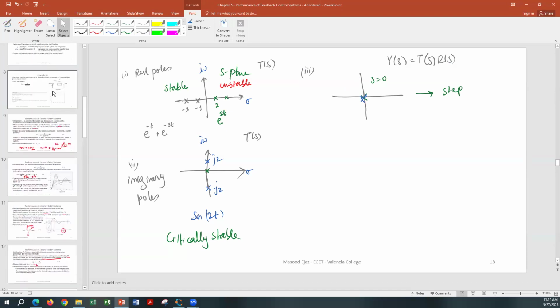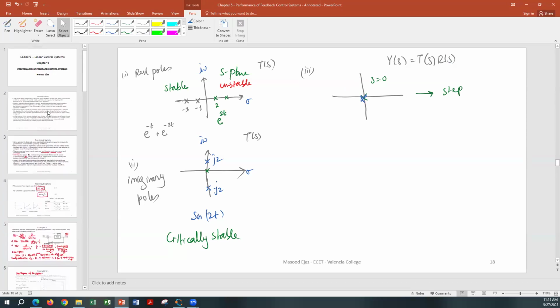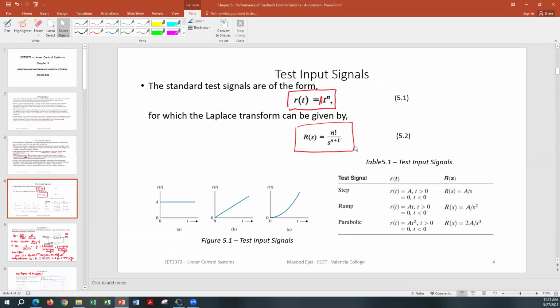If you look here at the beginning of this chapter, right here, 1 over s square is going to produce an output A times t. So if 1/s is coming from your transfer function and 1/s is coming from your Rs, then your output is going to be unstable. It's a linearly increasing output.